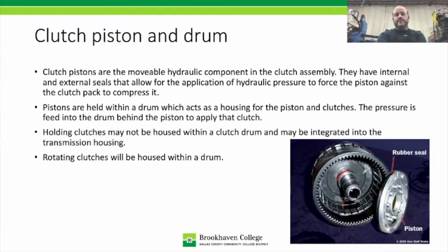And whenever the transmission determines to turn this clutch on, in this transmission it'd be third and fourth gear, hydraulic pressure is fed from the center of the shaft into this whole area, which causes that piston to move. Now this piston is made out of aluminum, but there are pistons that are made out of steel, and there are pistons that are composite. It'll be steel and aluminum together. For whatever reason, they decided that was the best thing in those applications.